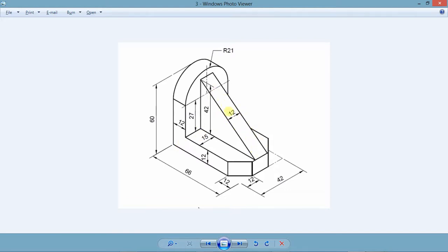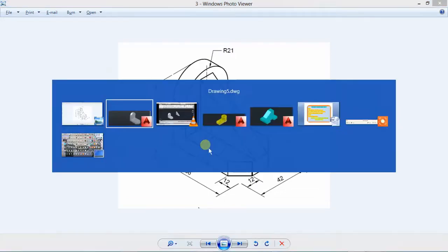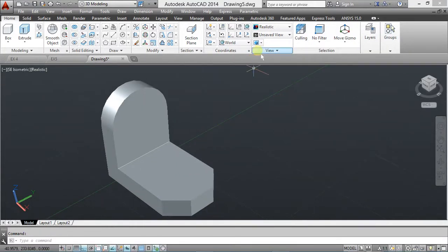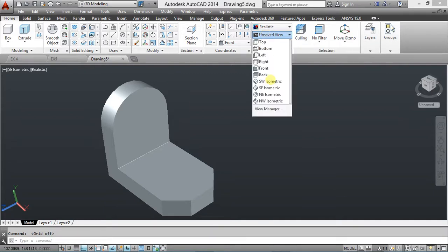this portion. You switch the UCS to the right direction. Okay, switch it from the front rather. This is the right, this is the front. Okay, to do that, come here. I'm going to switch here front, switch front. Okay, to have it like this. Now you can remove your grid so it will not interfere. Remember southeast.